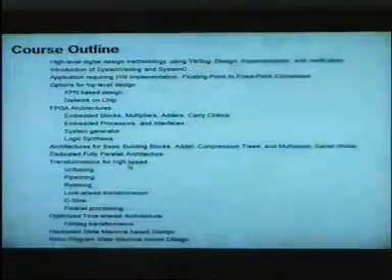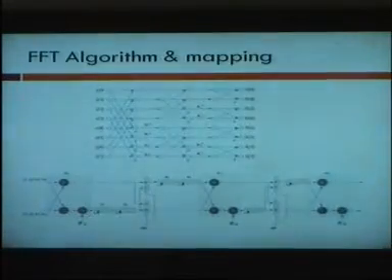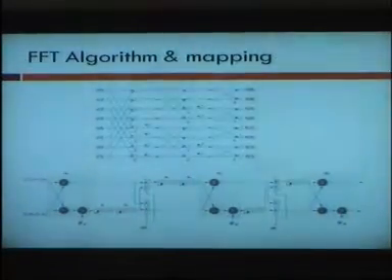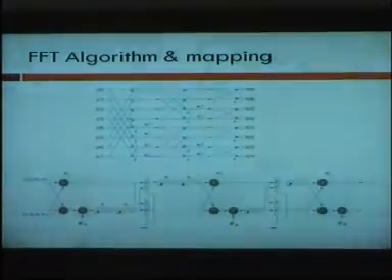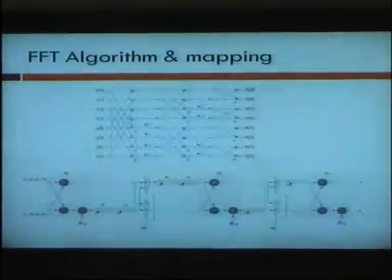We'll spend more time in the advanced stuff like the parallel architectures. Fully parallel means that the way you draw it, you actually implement it in the same way. So the easiest to design is this: the algorithm description in a flow graph. Just do the same in hardware. Wherever there is an addition, you put an adder.